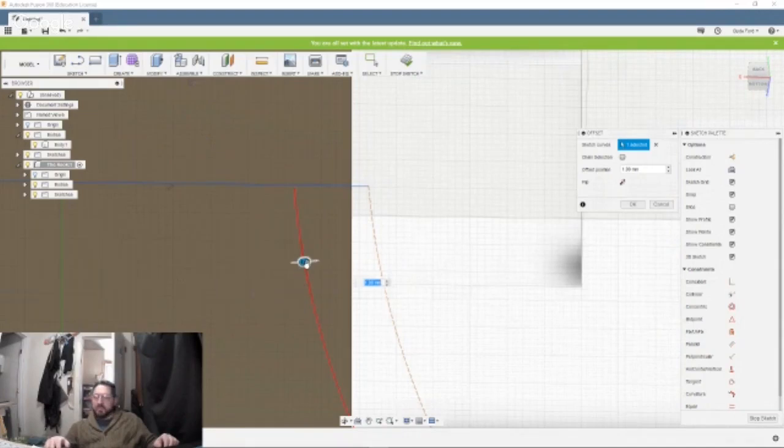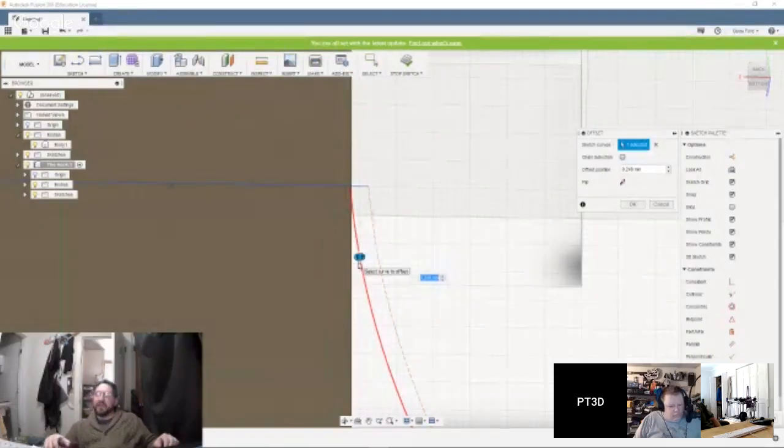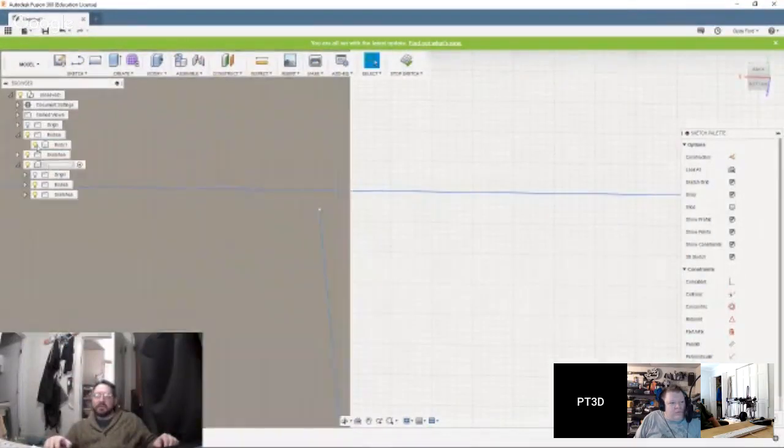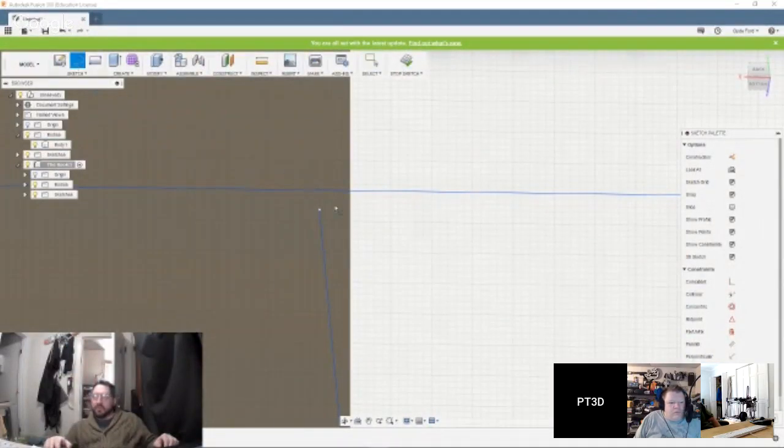Drag it over. And I would actually leave it just inside so you know it closes. That makes sense. Don't try and bring it right out to the edge. Leave it just inside like that. Yeah. You'll still have to connect the line, but at least it'll close it. Say okay. Now I can just go bleep, and then bleep, and we're done.